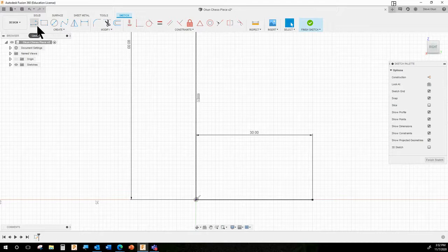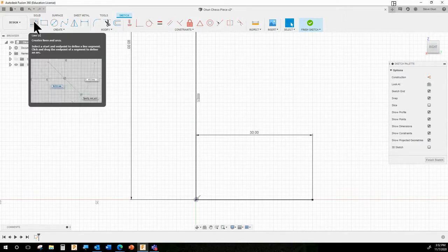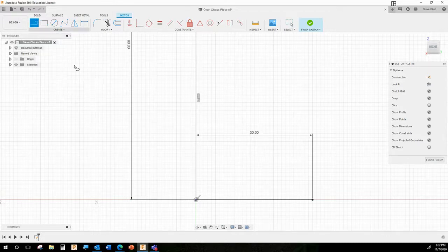Okay? To make construction lines, you use the same line tool. There's not a special tool. The first thing I want to do is figure out where 10 millimeters high is. And yes, you could count graph paper squares, but you don't want everyone who ever interacts with your drawing to have to count graph paper squares to see the drawing. You want to create these construction lines so that everything is obvious to them and they don't have to sit there and count squares. So I'm going to choose the line tool, and where you put this doesn't really matter.